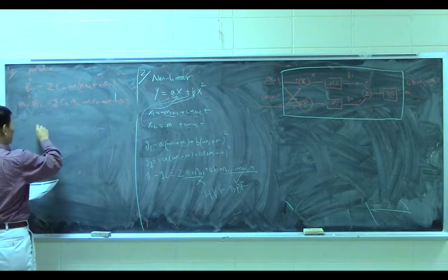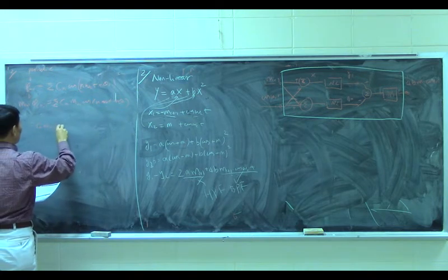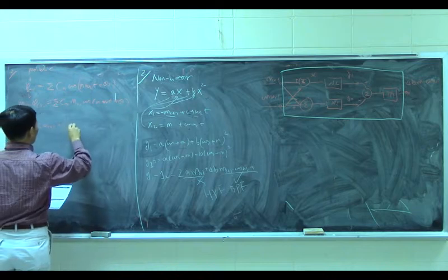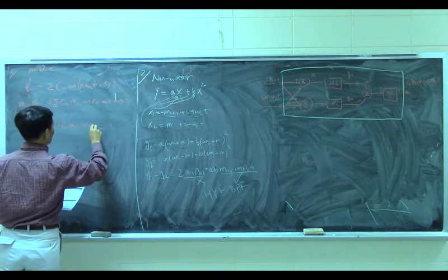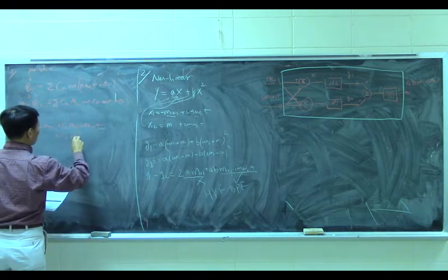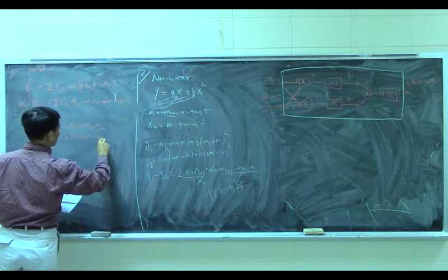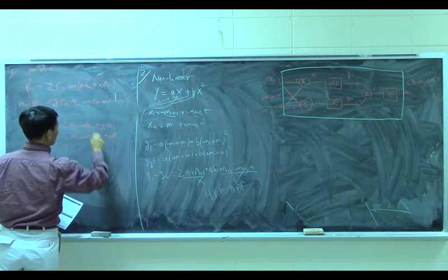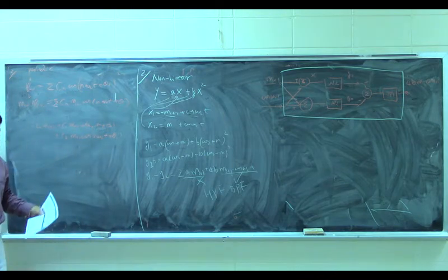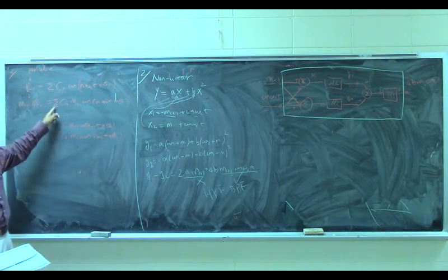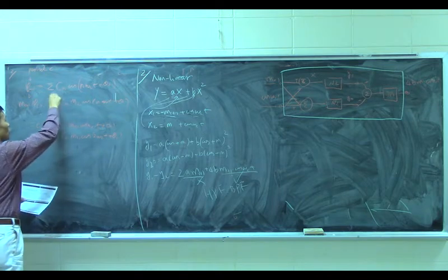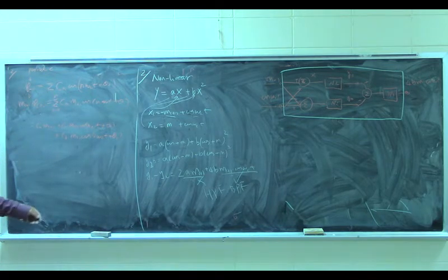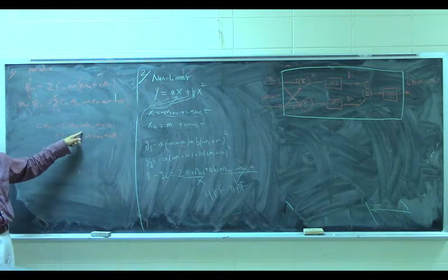So this one is C0 m(t) plus C1 m(t) times cosine omega_c t, plus C2 m(t) times cosine 2 omega_c t plus theta_0, and here plus zeta_0 or something, and from 0 to infinite terms. Again, what are we looking for? m(t) times cosine. Do we have that? Yes, here.